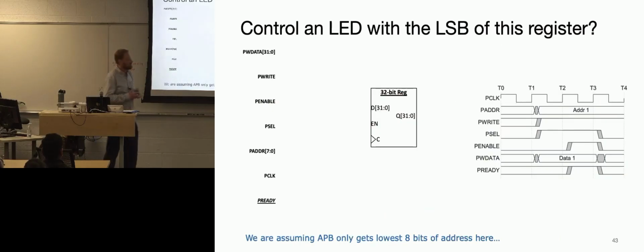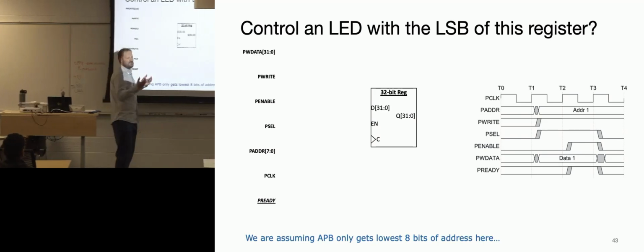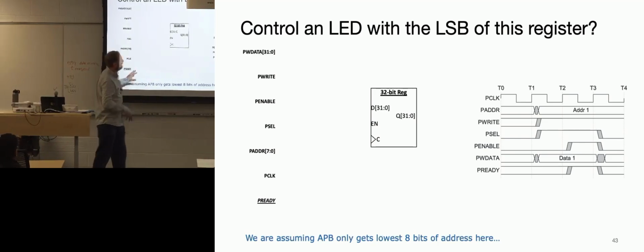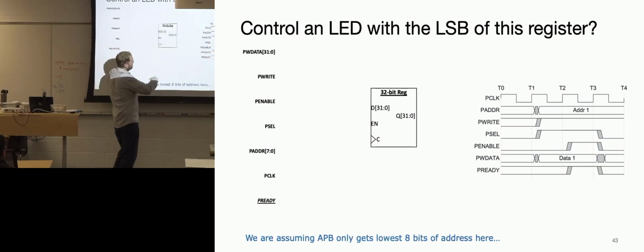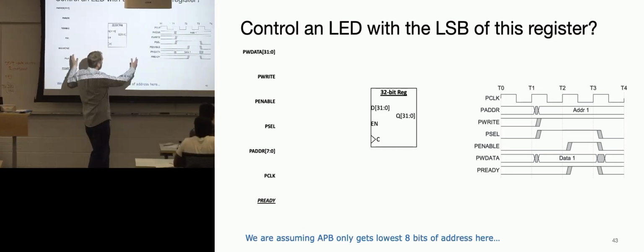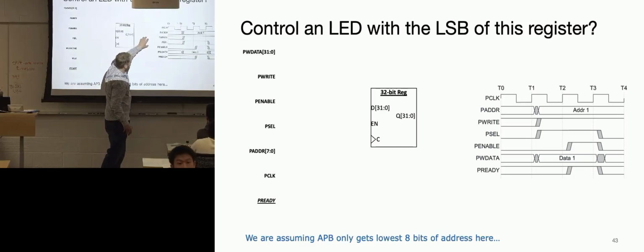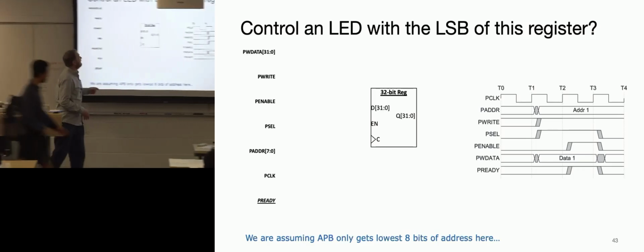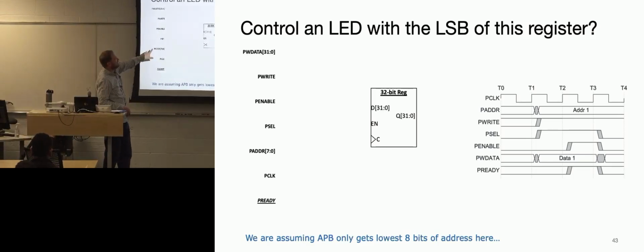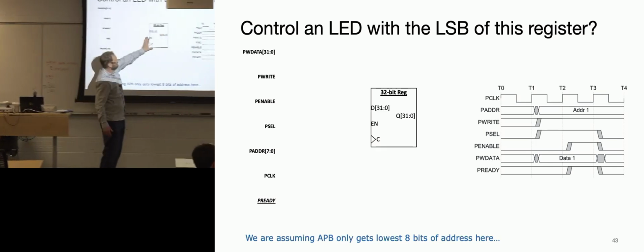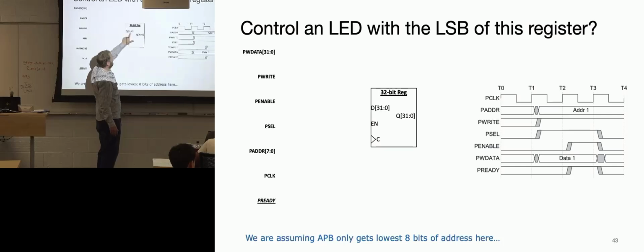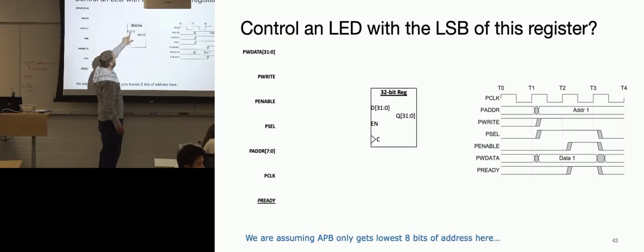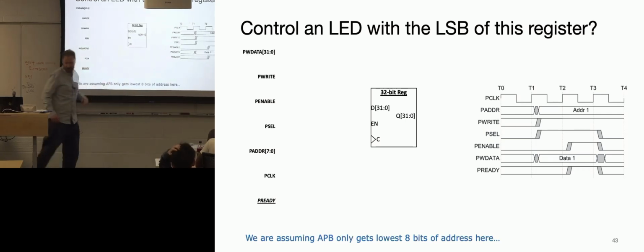And now what we're going to do is think about if you are the requester and completer. Your job is to write a completer, write that digital logic such that your peripheral, because a completer is a peripheral, is able to complete some tasks. So say we want to control the lowest significant bit of a register. A register here is like a 32-bit set of D flip-flops. We'll just designate this as a D flip-flop, but we're going to show that it has more than one by this nomenclature here. So here's showing the concatenation, and then we have the label 32 bits.